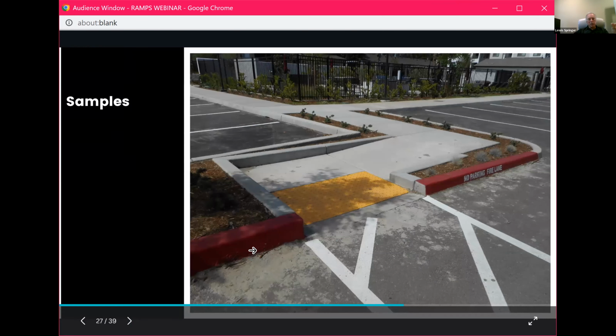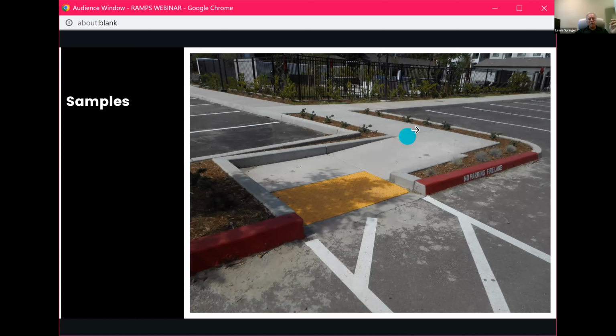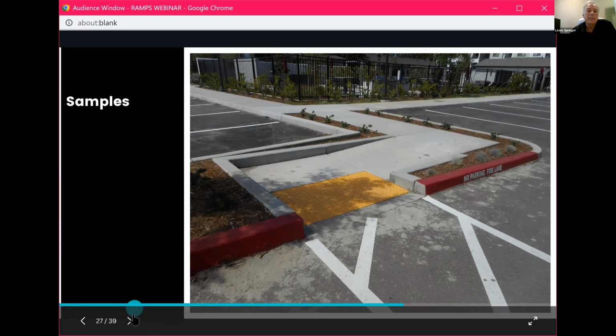So here's an example of that parallel curb ramp I was talking about earlier, where it's definitely a curb ramp coming down to a landing. It's actually compliant even under today's codes. We have 36 inches behind it, 36 inches detectable warning, but it is not in line with the sidewalk. So this technically becomes a top landing, although under the new code section, it doesn't actually meet the requirements of a parallel curb ramp, which is that 406.3.1 section. Okay, next.